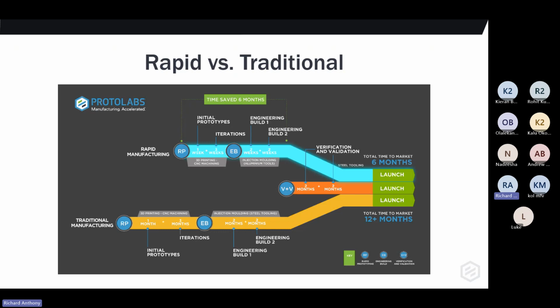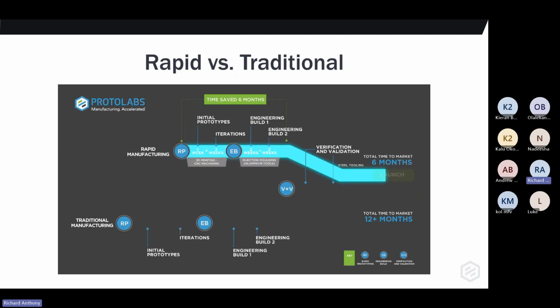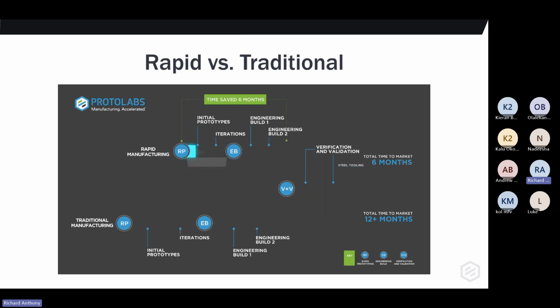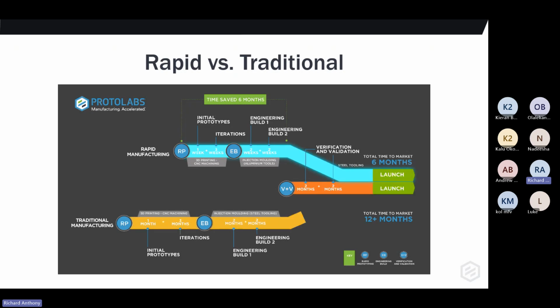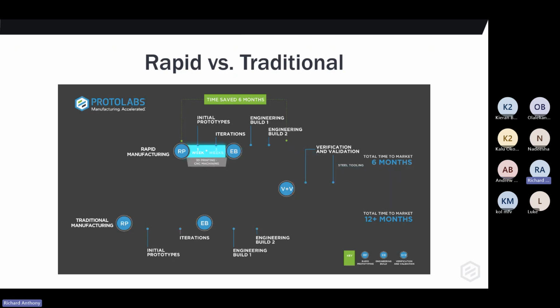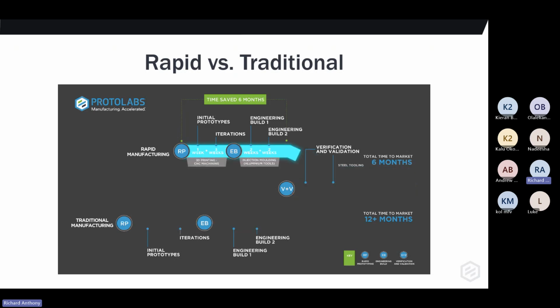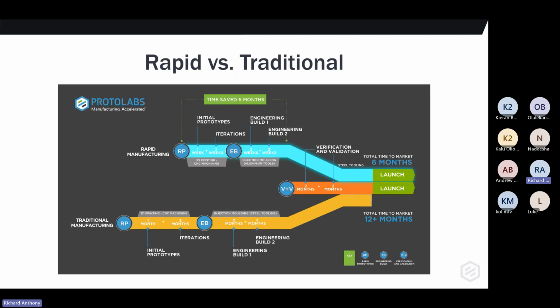So if you're having 10,000 parts plus, having that piece part price lower is a greater advantage because you can save more money in the long run, and paying a little bit more for the mold cost initially is usually less of an issue, and that additional mold cost covers the ongoing maintenance. So to answer your question, they're all aluminium mold tools, but if the durability and the longevity of the mold is a concern, then I'd advise you to go to that unlimited mold option, and then we look after that maintenance, and there's no additional charge.